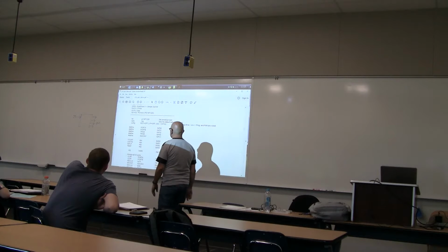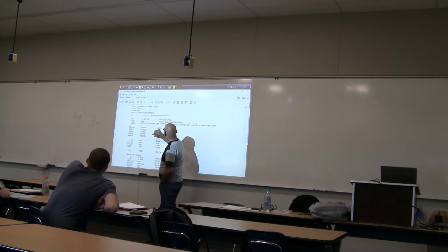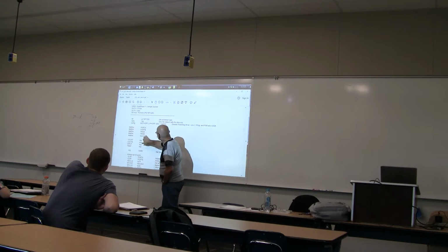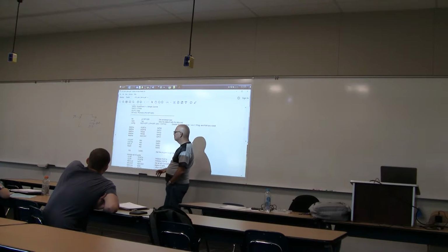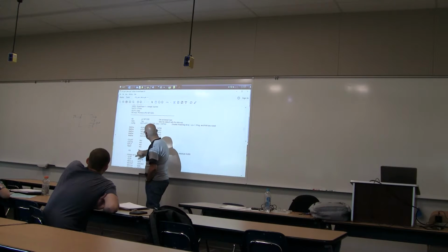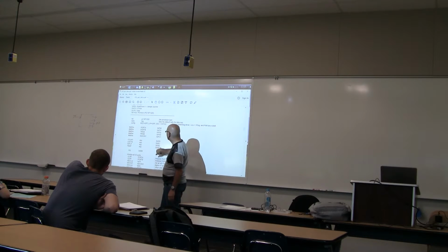All right, defines. Do you do defines in 121? Yeah. Okay, same thing. It's setting up a symbol. When I say PORTA, it will see 0xF80. It's just saying this is a shortcut, an abbreviation for whatever this is. These are similar. So count is just an abbreviation for hex 80. Last in is an abbreviation for hex 81, and so on.